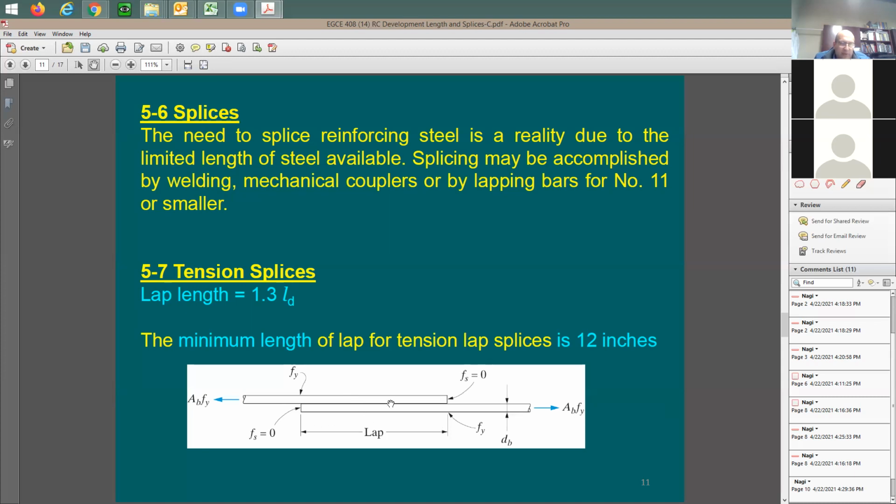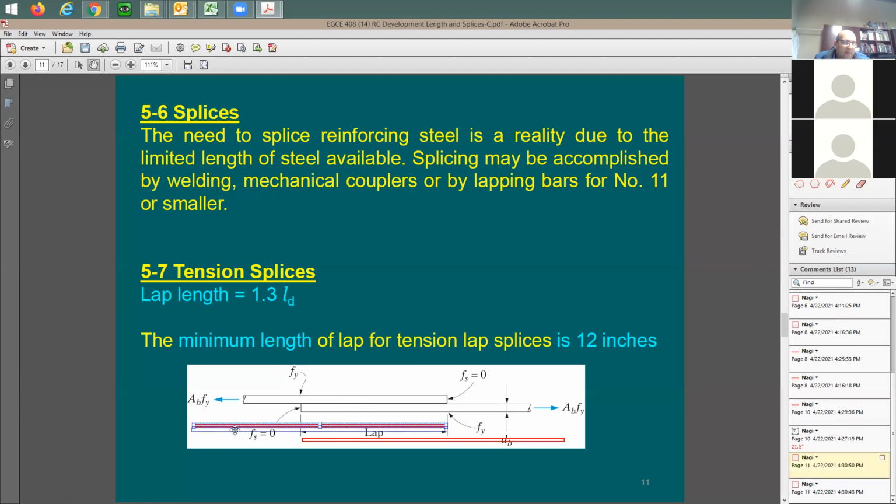There is no weld between the two. So actually you can have a little gap between the two. You can have one rebar to be here. Let me draw it this way. And the other bar is going to be right here. And you can leave a little bit of concrete between them, and this concrete is going to be, let's say, about an inch. They call this non-contact lap splice. When they touch each other, they call it contact lap splice. So I want to be sure that you understand there is no welding between the two. We are not welding the two rebars to each other.